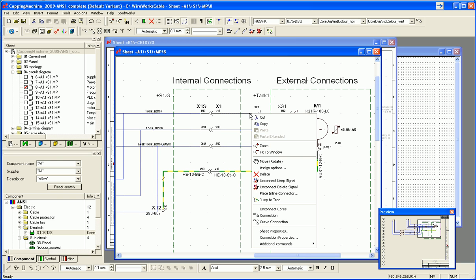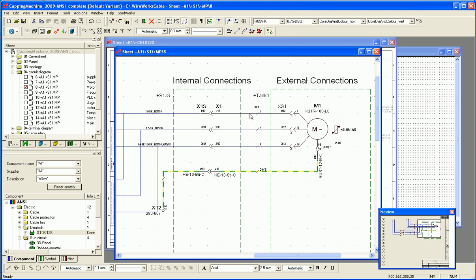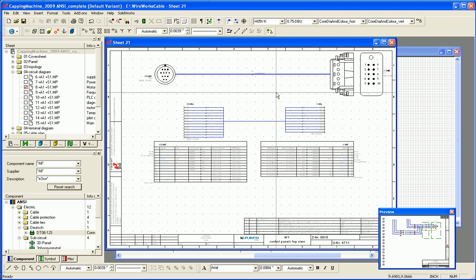Before we do that, I want to just run a tool off here. I select on this connect line here, go to the SolidWorks menu and create cable plan. We're able to produce a cable plan of the layout of this harness. So this is everything that somebody could actually use to produce this harness, with the pin-to-pin connections, what cores go onto which connector, etc., etc. The thing that's missing is the actual length.